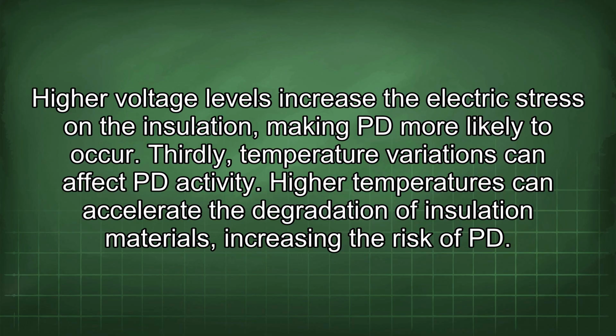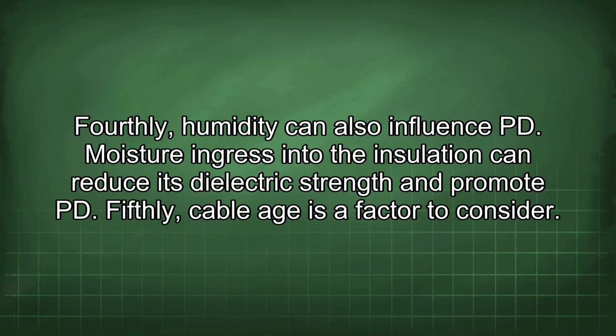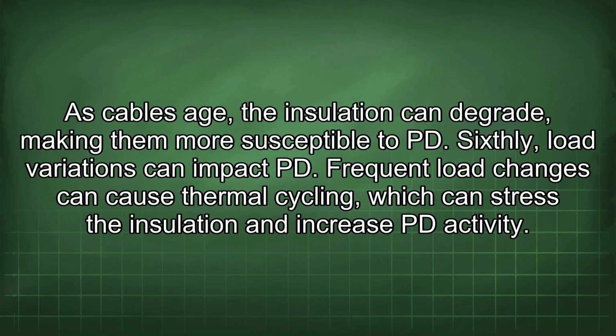Thirdly, temperature variations can affect PD activity. Higher temperatures can accelerate the degradation of insulation materials, increasing the risk of PD. Fourthly, humidity can also influence PD. Moisture ingress into the insulation can reduce its dielectric strength and promote PD. Fifthly, cable age is a factor to consider. As cables age, the insulation can degrade, making them more susceptible to PD.